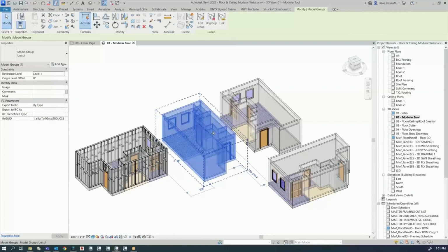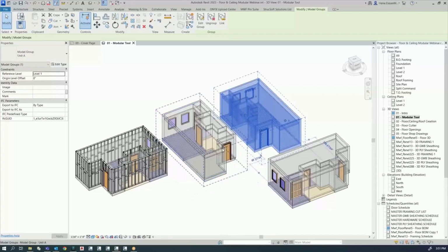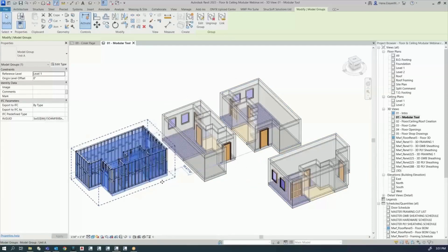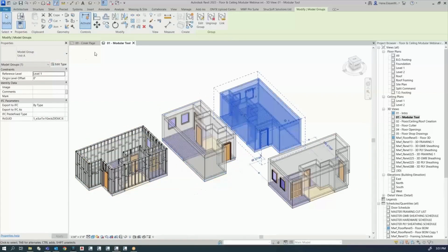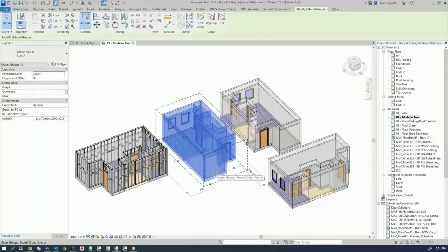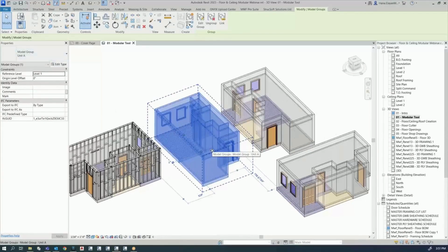In Revit terms, this would be a group, just like what we have over here, and it's being repeated. Over here, you'll see that it's mirrored. Here, it's been rotated, and here, it's another one, but you'll notice every time I click on any one of these, it's really the same group. So to make life easier, if you needed to use a repeated pattern, you can use Revit groups. This helps you when you want to make a change. It applies to everything. Let's actually try it.